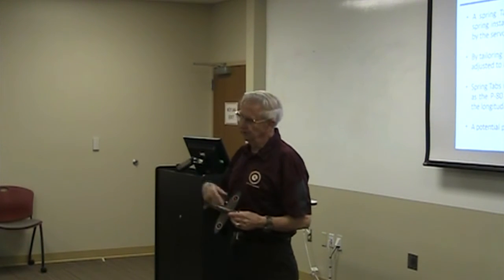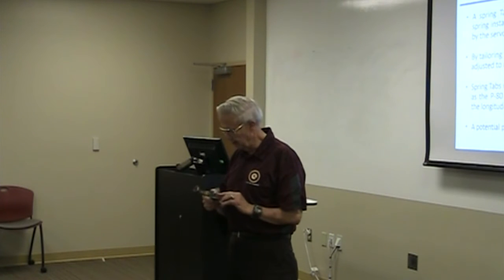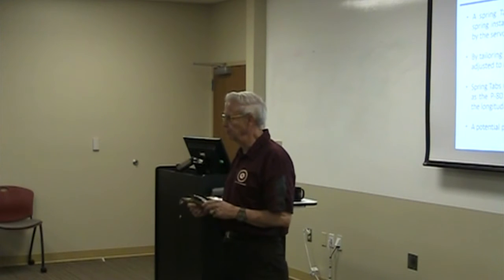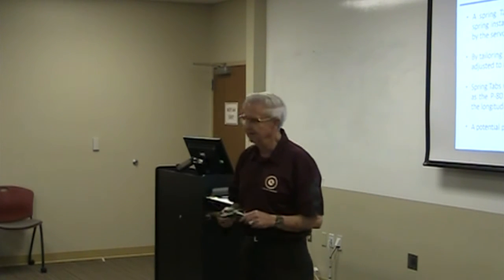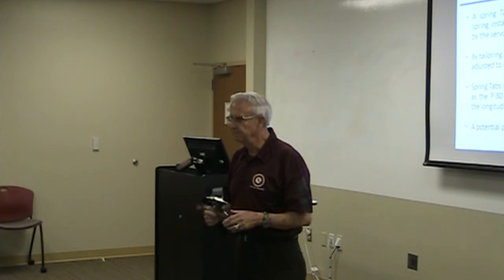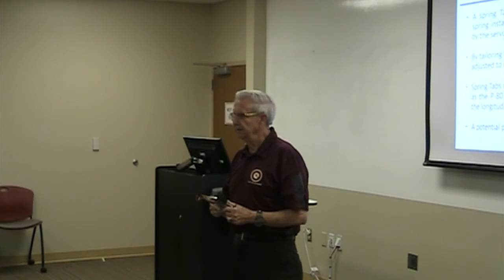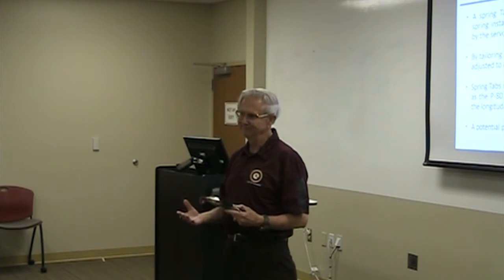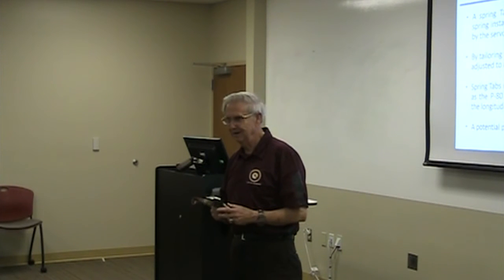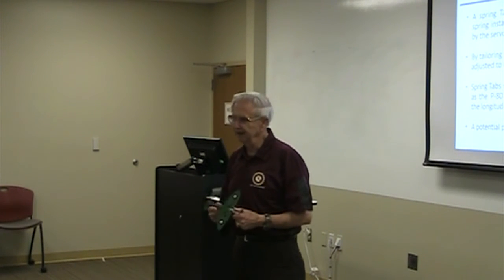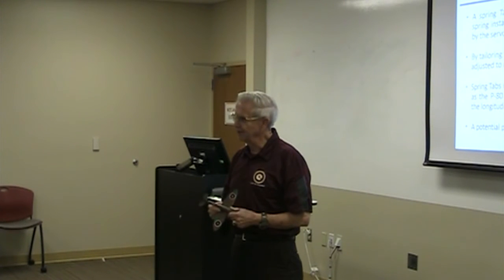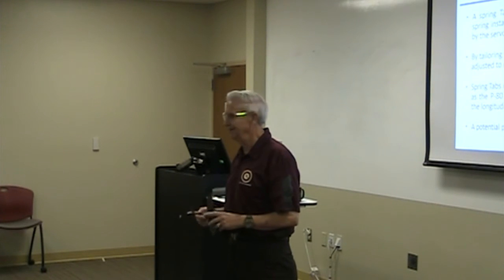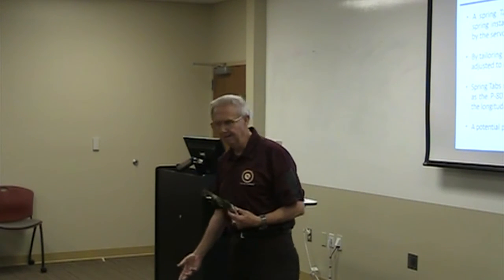But we put a half horizontal tail in the tunnel out at what was then the B-1 division of Rockwell in Los Angeles, now Boeing. This was a flutter tunnel that had an automatic shutdown device that, when it sensed the flutter starting, would shut the tunnel down. Well, in the case of this tail, it wasn't fast enough. The tail went down the tunnel and did $1 million worth of damage to the tunnel.